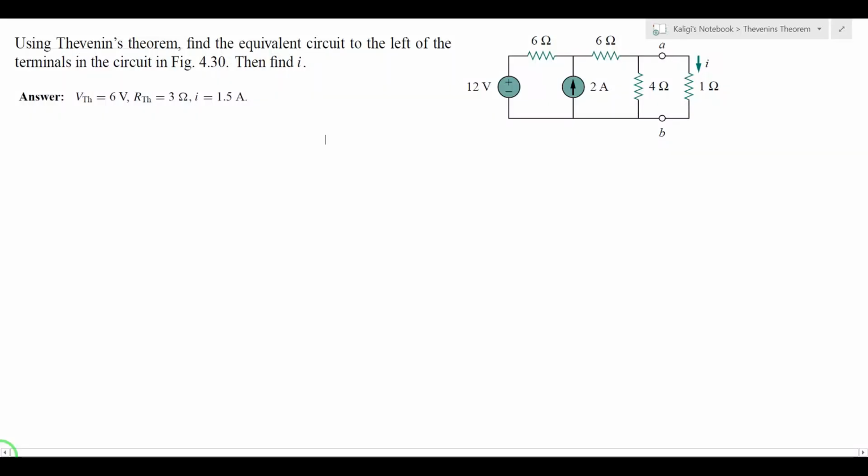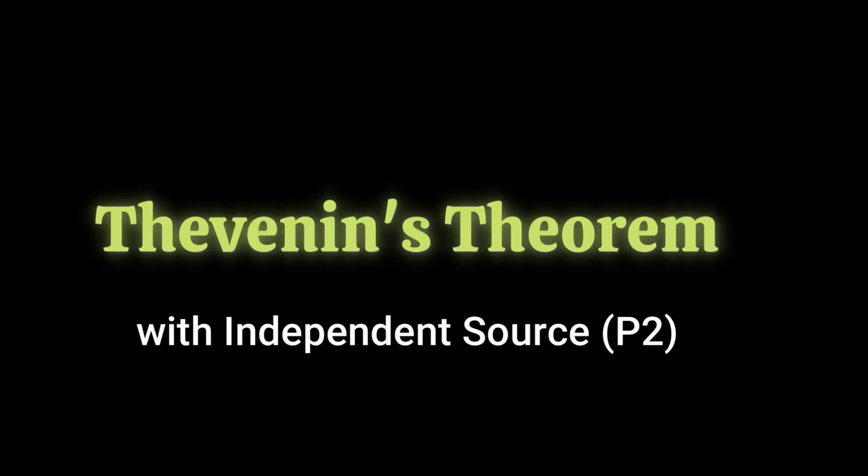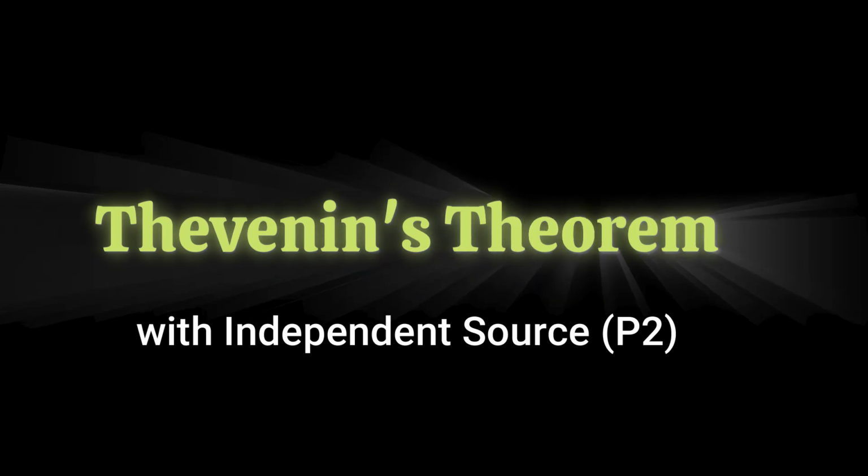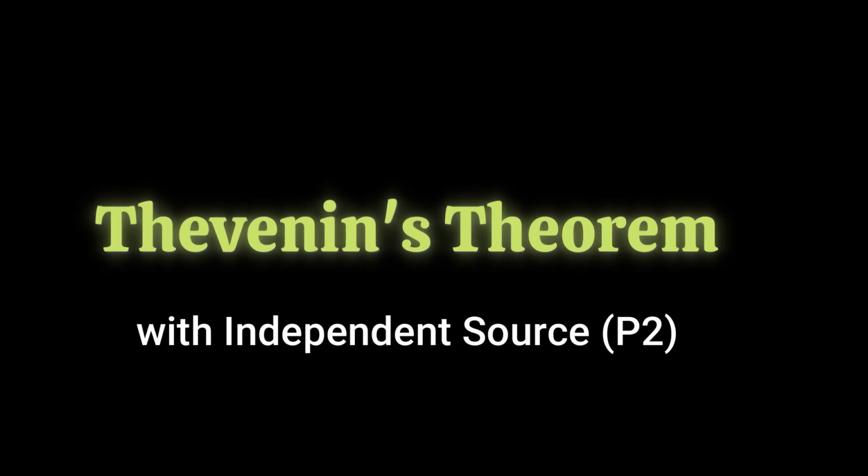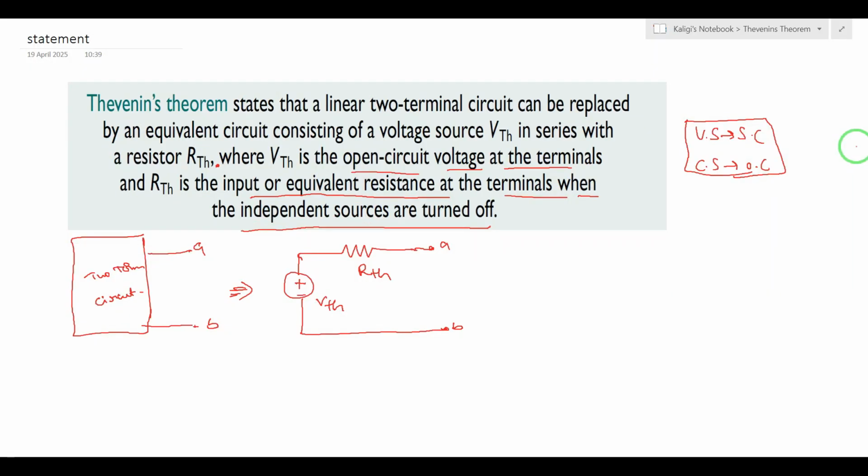Hey guys, in this video we will learn how to use Thevenin's theorem to solve any circuit. Thevenin's theorem states that a linear two-terminal circuit can be replaced by an equivalent circuit consisting of a voltage source VTH in series with a resistor RTH.